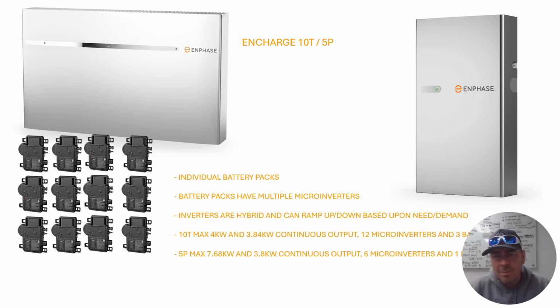So the 10T would have more battery capacity, twice the capacity of the 5T, but the 5P has twice the capacity of output for the instantaneous power for the surge, right? A surge of power is needed to start up a device, which makes it good for higher demand appliances and components, while the 10T would be better for long-term stability because it's a bigger battery capacity.